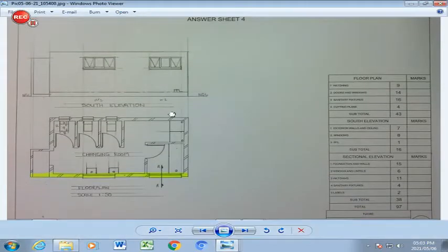We are now going to turn our attention to this area over here where we are going to cut only through this wall with the window up until the ceiling. And it's very important that you now need to change your focus from a scale of 1:50 to a scale of 1:20. I want to reiterate, we will have a scale of 1:20 as it is a detailed section view. So it will be a cut right through the foundation, through the floor level, through the wall, through the window, up until the ceiling.